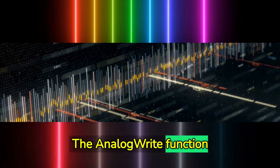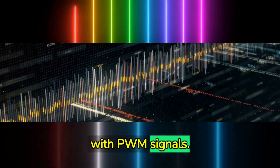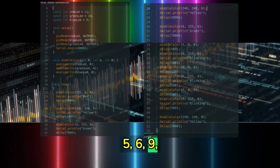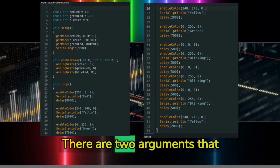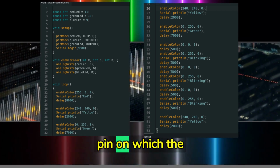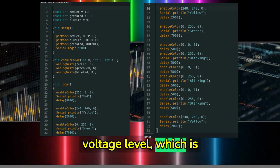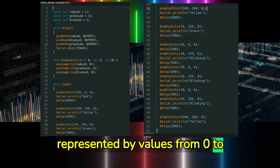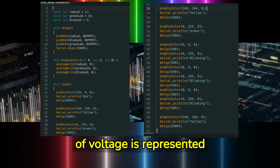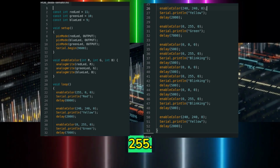The analog write function allows controlling the voltage on digital pins that can work with PWM signals. These are digital pins 3, 5, 6, 9, 10, and 11. There are 2 arguments that this function has. One is the digital pin on which the PWM signal is generated, and the other is the voltage level, which is represented by values from 0 to 255. The absence of voltage is represented by 0, while the maximum 5 volts is represented by the value 255.